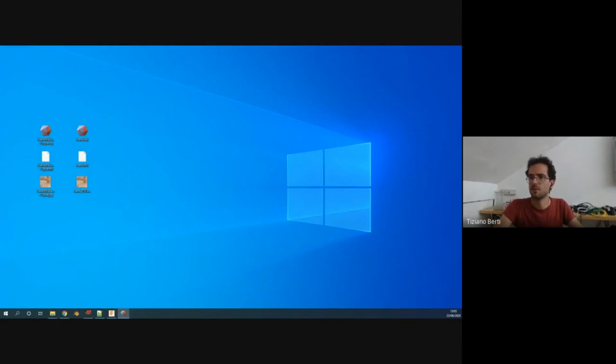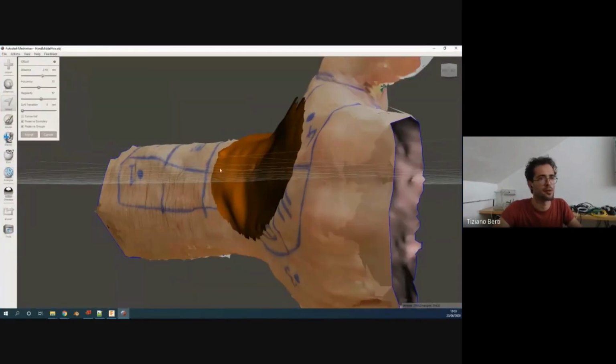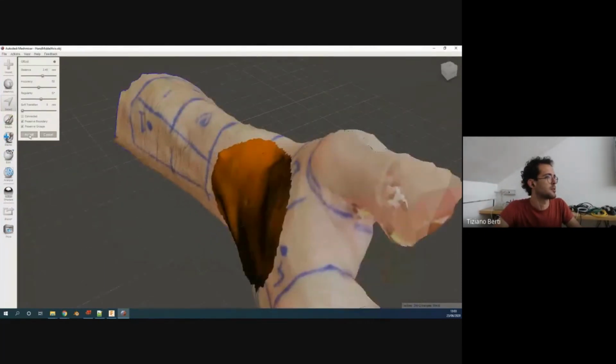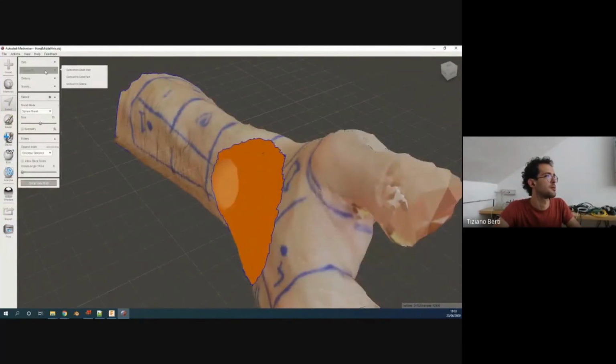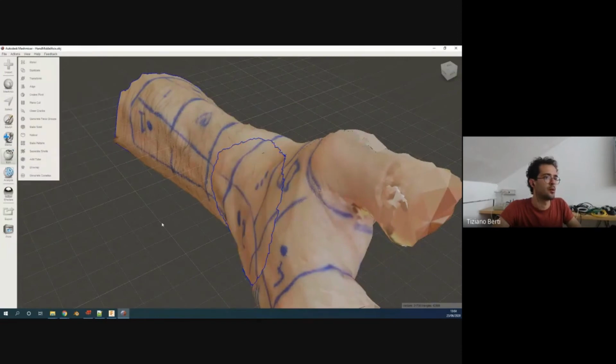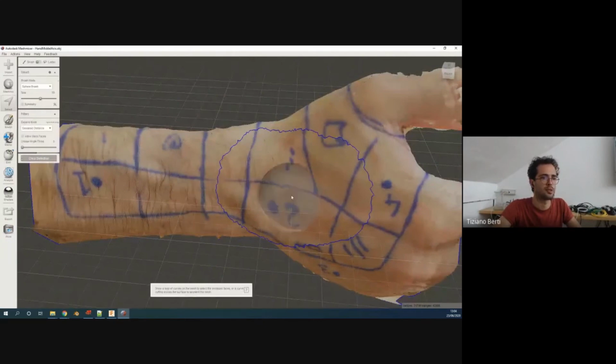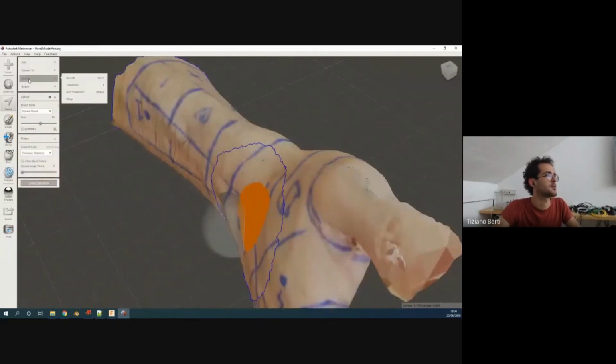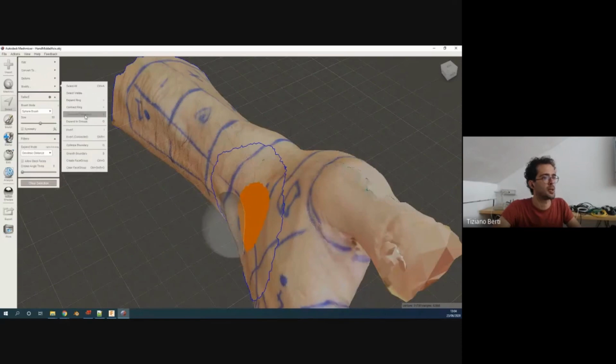So we have probably switched back a lot of time. So basically what we were doing right now was just selecting, edit, making an offset of distance a bit more. Sorry, I was working on the wrong one. So we are making this offset, accept, edit, separate shell, or we can make something which is a bit easier for the program to calculate. We can select a place and say expand to connected part.